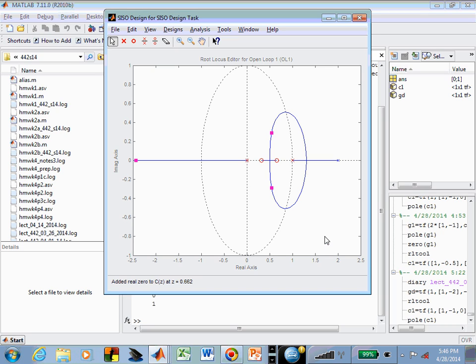now we're looking like it might start to produce something that will work. Is this a stable closed-loop system, as shown? And how do you tell that? You're looking for your 3 magenta squares, aren't you? Those are showing you the locations of your closed-loop poles. And you've got one way outside the unit circle beyond -2, almost -2.5. So this is now unstable, but you might be able to stabilize that if you lowered the gain.